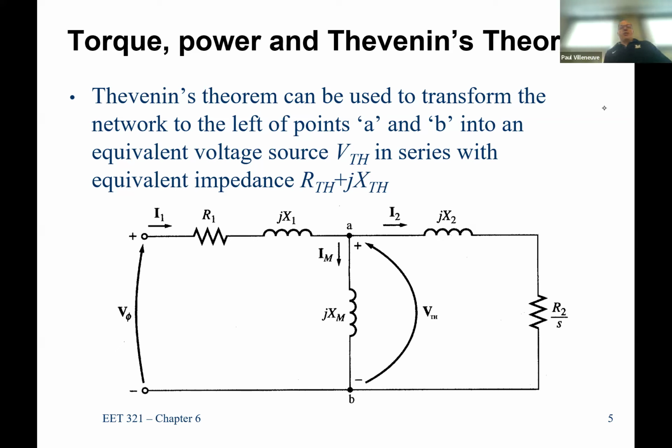You could do nodal for sure. The difficulty with nodal is you don't know this voltage and you don't know that voltage, so it makes it more difficult. And the other thing is, if I know the current through here, I get all those losses really quickly. I don't know if my pen is dying or what. If I have those, I can directly calculate losses. If not, I have to calculate the voltage on each side of the resistor and then do V squared over R for the voltage drop. So there's more work to do. Usually calculating power losses is far easier with current than with voltage. But don't worry, we'll be using nodal analysis a lot moving forward.